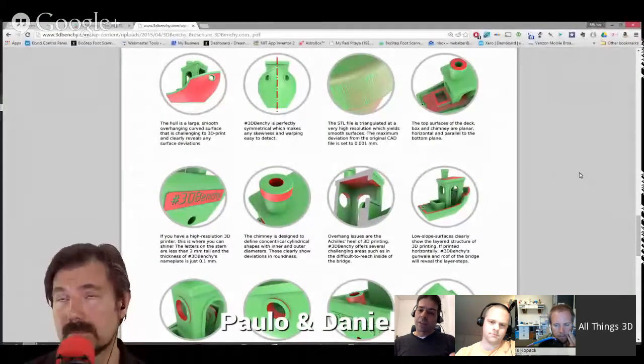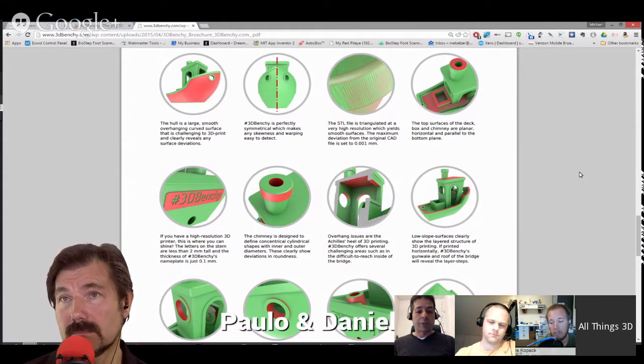And this can actually show you the difference between a multi-directional cooling fan and a unidirectional cooling fan. Most 3D printers have only one direction from which the cool air cools the PLA plastic, if you're printing in PLA. So symmetry is good to have.